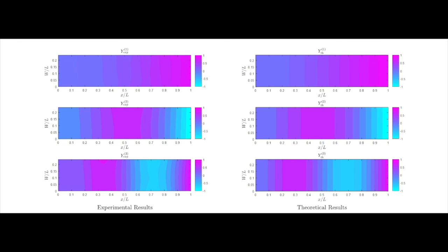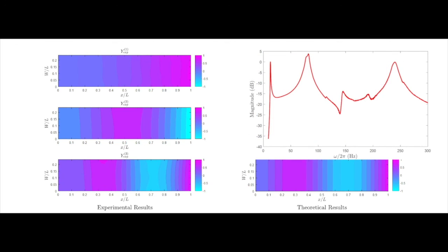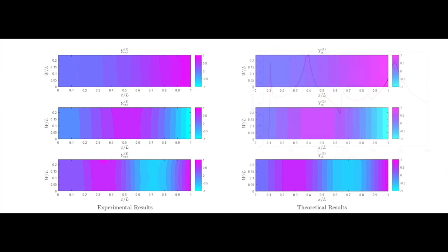Furthermore, the tested specimen has a lower length-to-width aspect ratio, which causes it to act more like a plate. This is seen in the frequency response function, as one mode at 140 Hz due to twisting was noticed. In general, however, the modes agree to a great extent with the theoretical predictions.